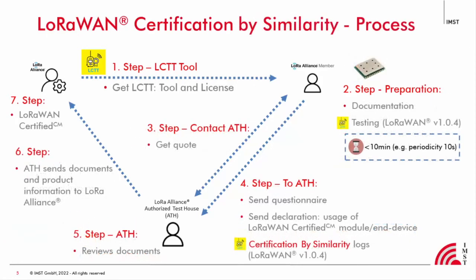If your product is based on an already LoRaWAN certified module, you may request the LoRaWAN certification by Similarity, which simplifies the LoRaWAN certification process. The main difference here is that this process does not require any testing run by the authorized test houses. Only a quick testing using the LCTT is needed in case your product is compliant with the LoRaWAN version 1.04. This could be run by each member and ensures the correct integration of the certified module.